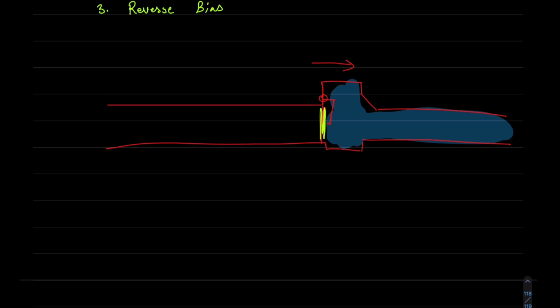Nothing happens, because the check valve checks that the water only flows in a single direction. So now, the only thing water will do is push the check valve more until there are only two possibilities: water will stop or the check valve will break.